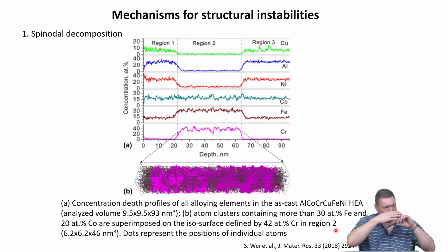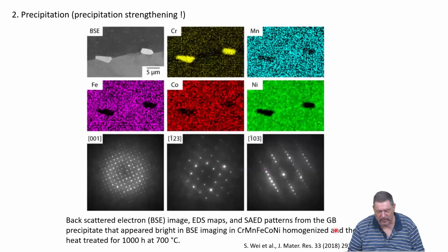That means it's separating automatically, you cannot prevent it. It's an unstable condition, not a metastable, an unstable condition. Every fluctuation will serve to go downhill, meaning precipitates will form, two phases will form, which have different compositions. Or obviously precipitation, right? So you could get a new phase.